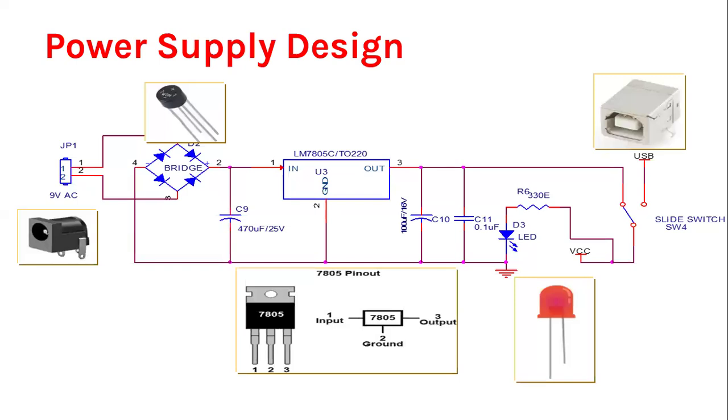And the next thing, guys. Any type of LED requires 10 to 20 milliamperes of current. For the safe zone, 10 milliamperes of current is sufficient. So remember, guys: suppose you choose the IO component as an LED and the LED color is red, so the red LED requires 3.3 volts to 3.5 volts.